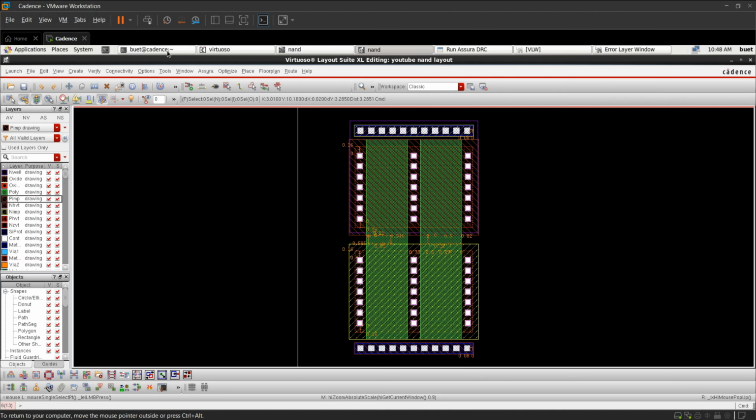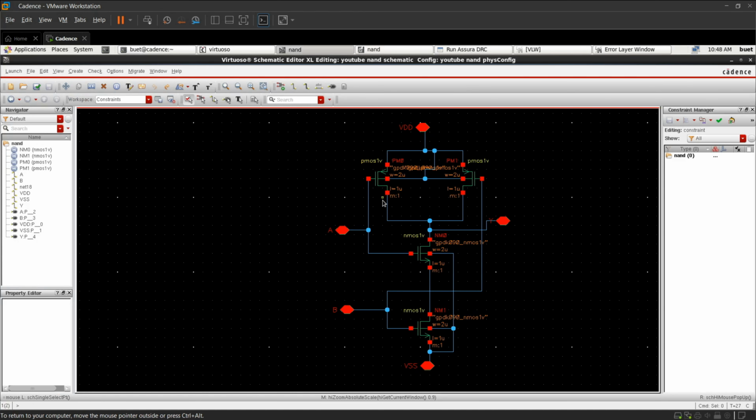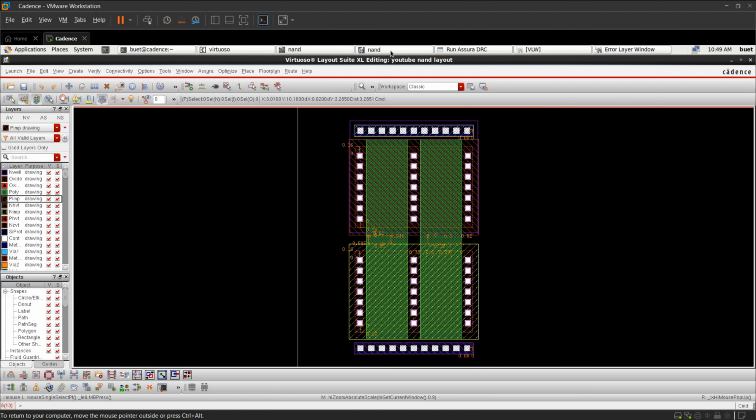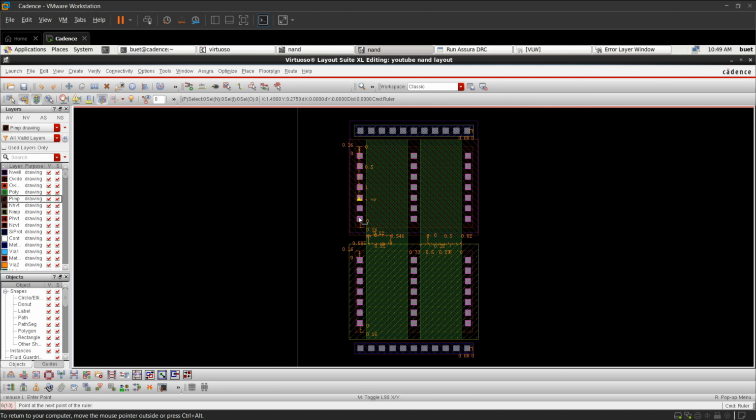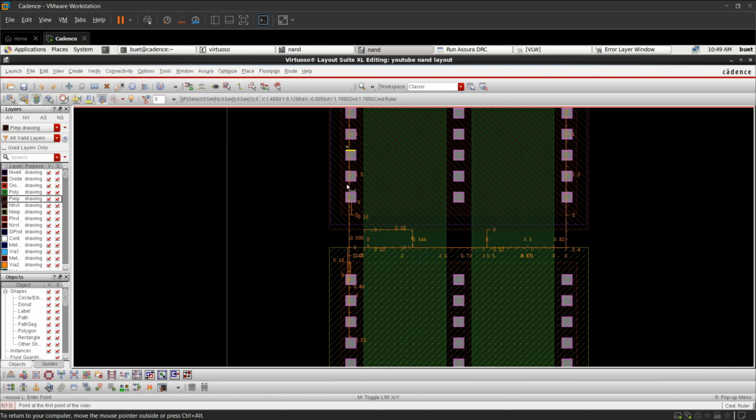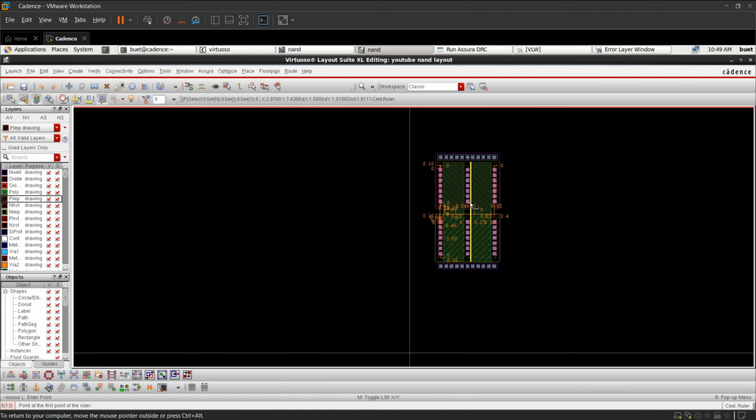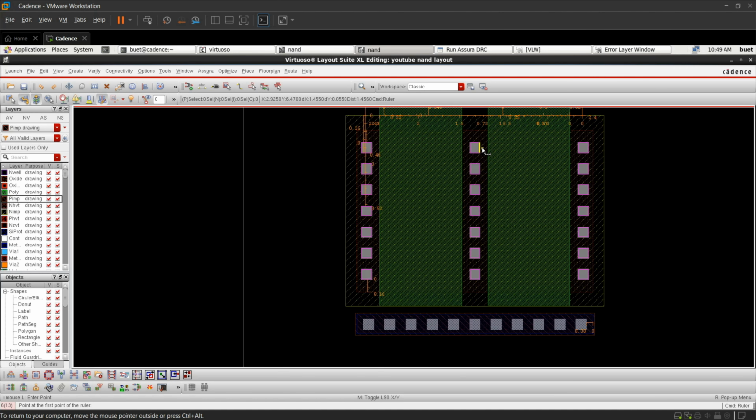Next thing, go to schematic. Yeah, the drains are also getting shorted, and those are given to one of the drain terminals of NMOS. Okay, so both of these should be shorted. Let me draw. This has to go onto this drain terminal of NMOS 1. This has to be shorted like this and connected over here. Hope you got this. Both drains have to be shorted with metal one and given that input to here. Okay, and in similar fashion this has to be connected.